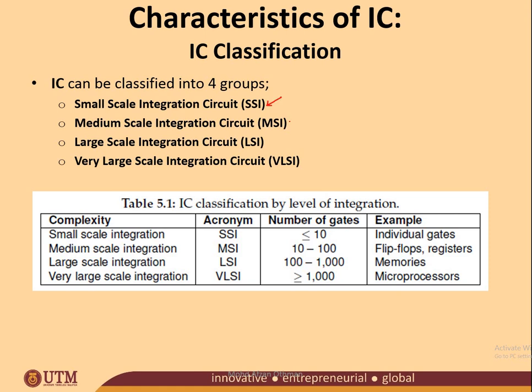And medium scale integration contains, for example, a multiplexer, decoder, or register. For the large scale integration circuit, LSI, sometimes it can be a small microprocessor, programmable logic device, and small memories. VLSI is a microprocessor.